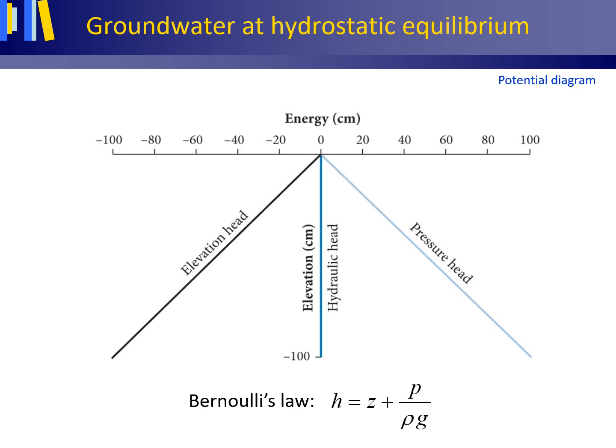As the hydraulic head everywhere equals the sum of elevation head and pressure head, the hydraulic head in the saturated zone at all elevations equals 0 and thus is independent of elevation. As there are no differences in hydraulic head with elevation, there is no groundwater flow in the vertical, which is in agreement with our starting point, which was hydrostatic equilibrium, that is, no vertical groundwater flow.